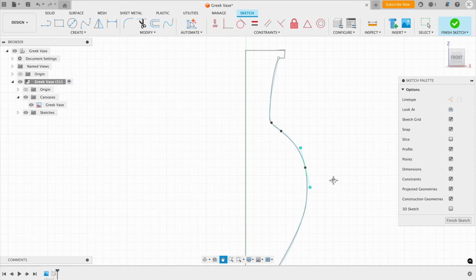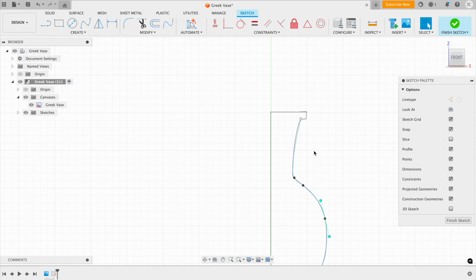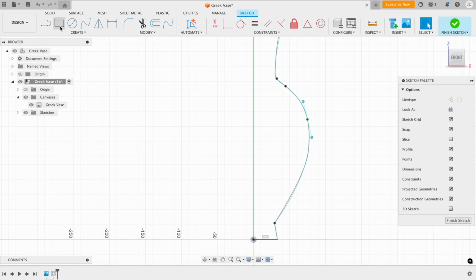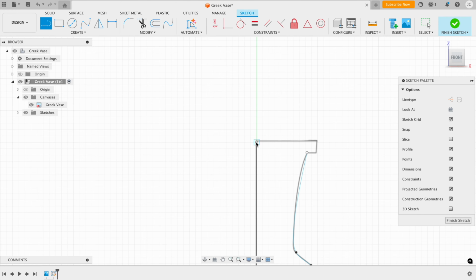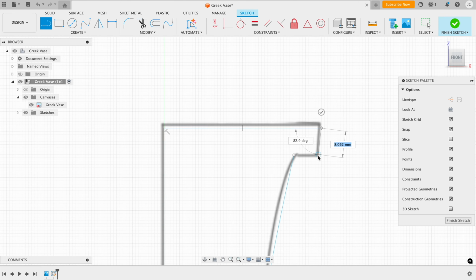And then once that's done, we want to finish off this sketch, so we can use the line tool. So then we click the center point and we draw to the top, 300 millimeters. And these just want to be normal lines. Now we draw another line to draw it across, and draw down the part to connect up these lines. I press the Escape key and then I click OK.